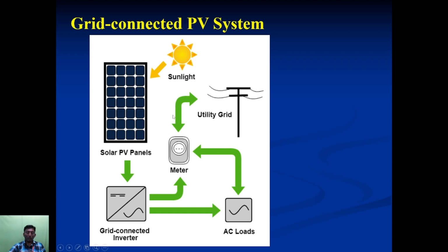Okay, through the net meter we will transmit the excess amount of electricity to the grid. This meter will note down or record how much electricity is applied to the grid. So this is one way of usage: panel, inverter, meter and grid.